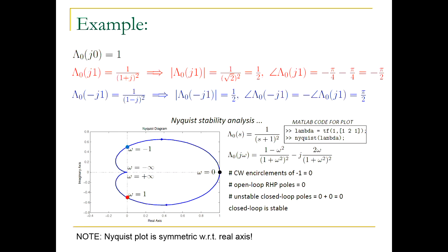So now, what is the number of clockwise encirclements of the minus 1 point, minus 1 j 0? This point, minus 1 j 0, is somewhere here. Are there any encirclements by this graph of this point? No. The point is totally outside. You remember, my C is outside the track where horses are racing. So I'm sitting here, so there are no encirclements, right? By the way, here the number of encirclements is 0, because we read it from the graph.